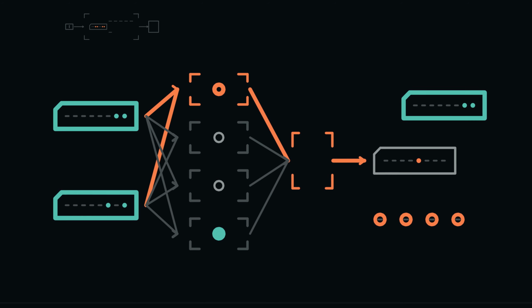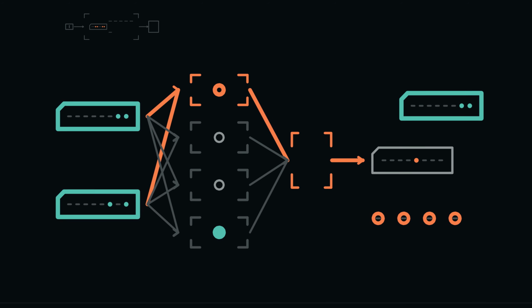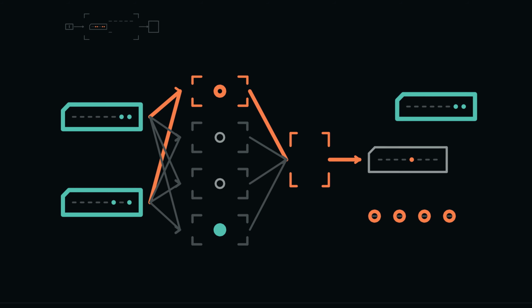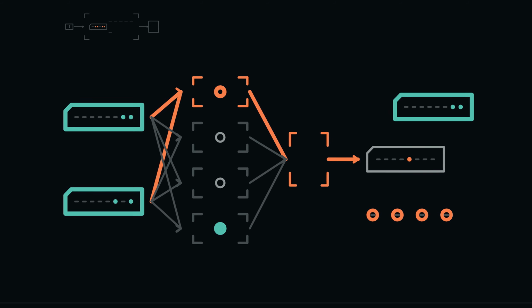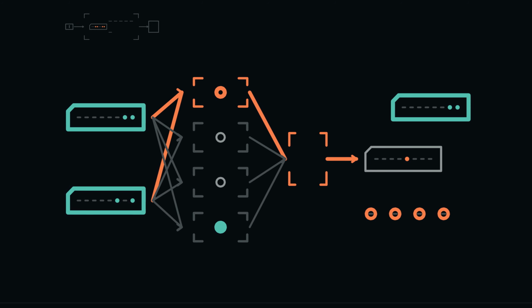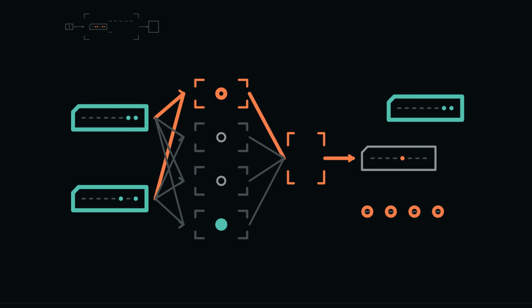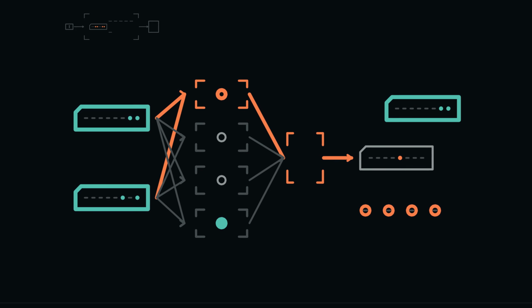The ALU does not remember the selected answer. It continuously relates current inputs and control to current outputs, subject to physical propagation time. The result register and flag register provide the before and after boundary. Before the clock edge, old architectural state remains authoritative while the candidate output settles.